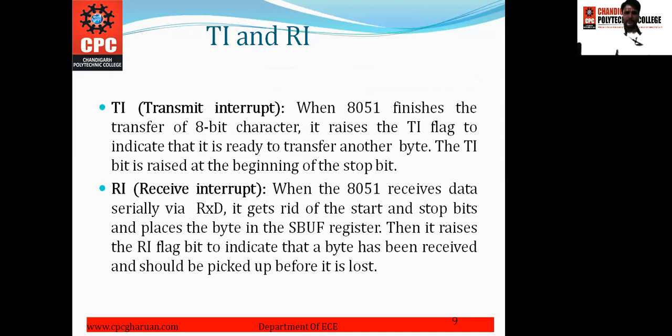Next is the TI and RI, that is the transmit interrupt and receive interrupt. The TI bit is raised at the beginning of the stop bit, and the receive interrupt is raised as the RI flag bit to indicate that a byte has been received and should be picked up before it is lost. This is all about the serial port operation of 8051.